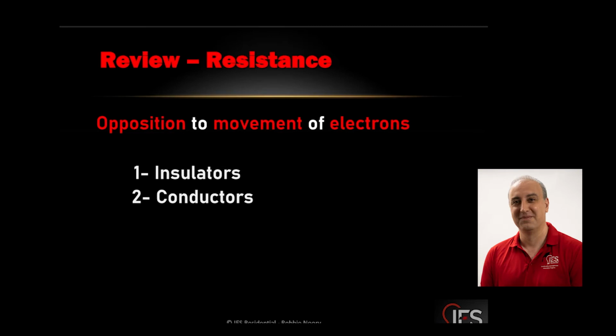This is why you've got to be aware as an electrician of what the system is, what the voltage is that you're working on. Because yes, air is an insulator when we're dealing with 120, 240. But at 480, 600, 1,000, 2,000 volts, that changes. This is why in many cases we have to label equipment with the PPE that's required to work on those systems, because once you put enough voltage, put enough electrons, they want to jump through the air, they will.